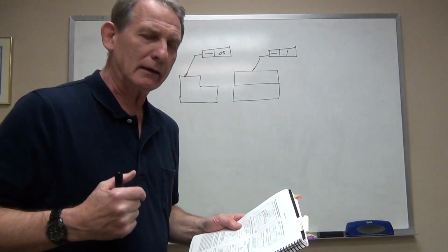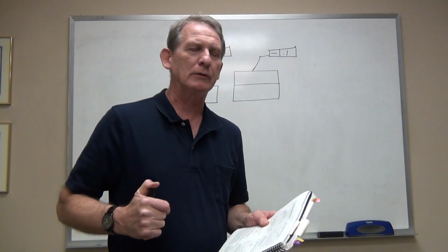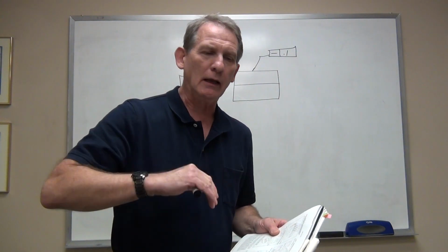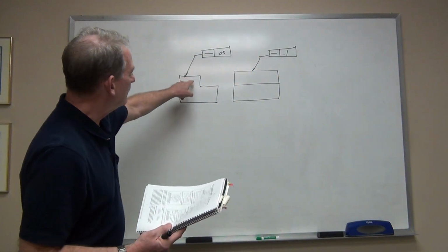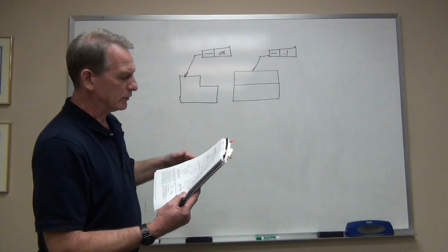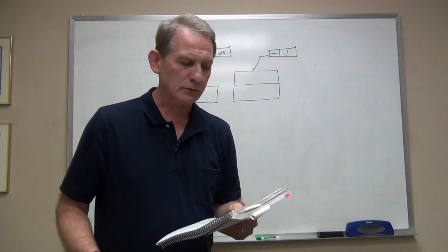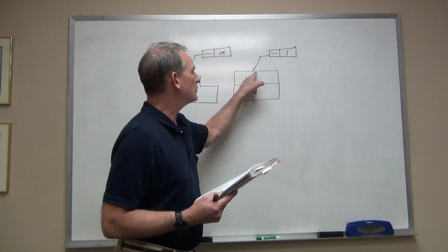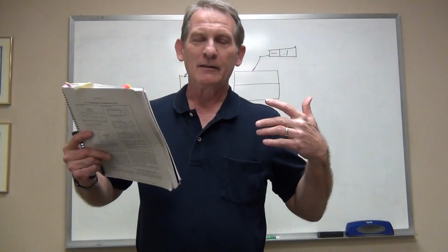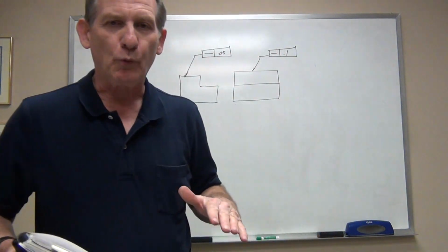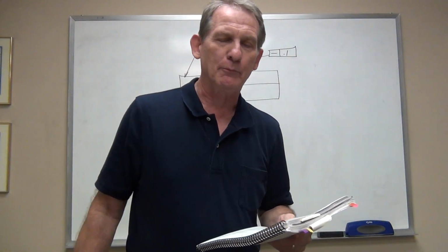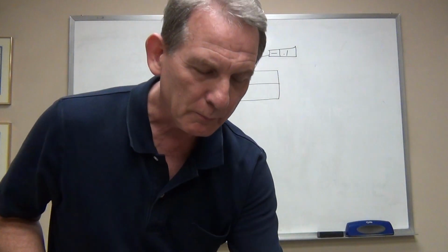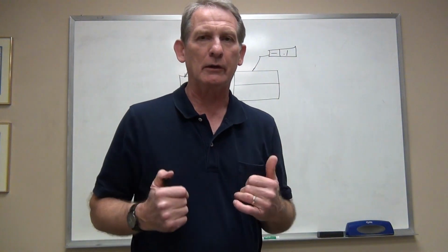What's going on here though is kind of interesting, and again is a consequence of the fact that we are controlling a planar surface by individual lines. If you look at the left side view here, you'll see that there's a tolerance zone of 50 thousandths on this surface and 100 thousandths on this surface. Well, in reality, that's all one surface. That is one flat face of that block. So how can we have two different tolerances on there? Because we are controlling them as linear elements.